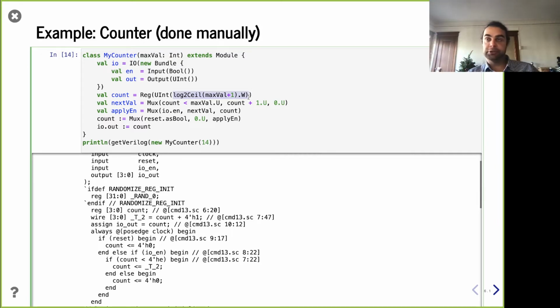There was a question in chat, which I think was well answered by another student, but I'll repeat this for the recording, which was asking, hey, wait a second, I went through this effort of having a mux here, and I had this special case of having a comparator and doing either +1 or 0. Hey, if I add 1 to 7 and I have a 3-bit binary number, doesn't it automatically roll around to 0? And the answer is yes. Yes, it would. However, if your number is not a power of 2, that won't work, right? So if you want to take that a step further, let's say you want to have a super optimized counter library, you could definitely imagine,